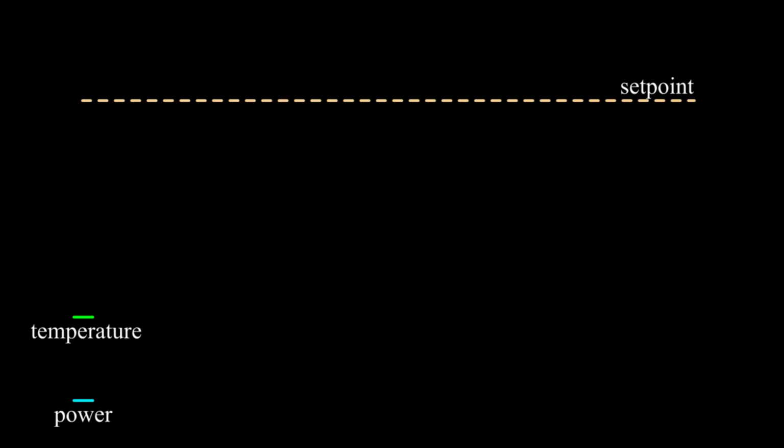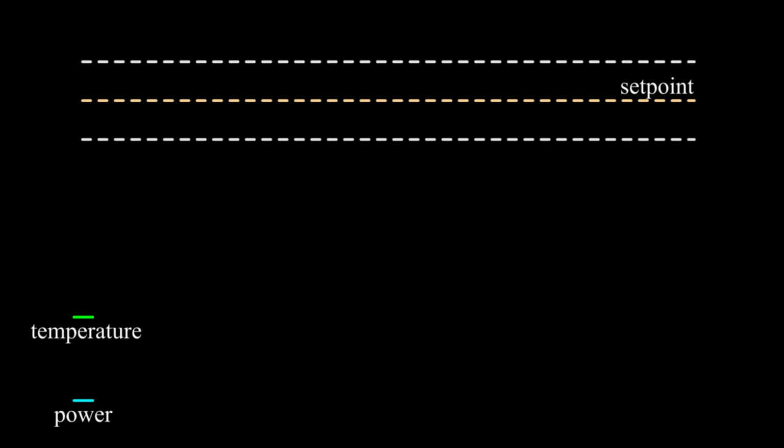We have power, temperature and set point. Around set point there is a space I call stable range, by default plus minus 15 degrees. Because stabilizing temperature is completely different thing than heating it up somewhere close to set point, in this area I use run-up regulator logic, here stabilizing regulator logic, and if temperature goes above stable range, I simply switch off the power. In order to get to desired temperature as quickly as possible, I set full power initially.